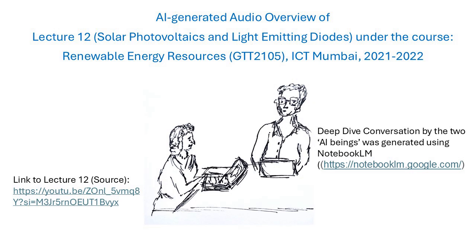So why silicon? Why did that become the material? Must have been other options. Silicon had some big advantages. First, it's everywhere. Second most abundant element in the crust after oxygen. Okay. Cheap and plentiful. And it naturally grows a thin layer of silicon dioxide, glass basically, when it hits air. That layer happens to have just the right optical properties, its refractive index, to act as an anti-reflection coating, helps get more light into the silicon.